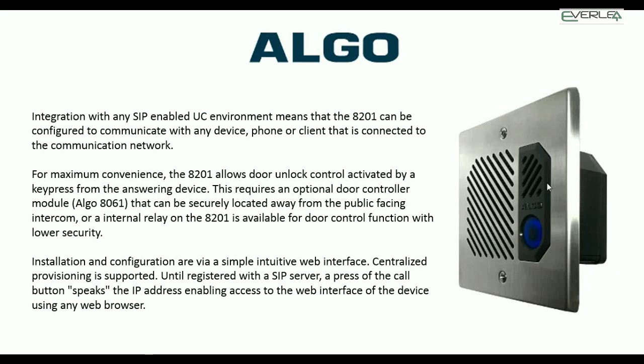The purpose for that would be if you wanted a more secure environment, so that you've got the 8201 intercom unit by the door, but to unlock the door, you want a separate controller unit for the relay. So if anyone breaks into the actual intercom phone themselves, they can't try and work out how to wire it and short it all up. Some building environments demand this, others not so much. So it's got the flexibility of setting it up any way you wish to do it.